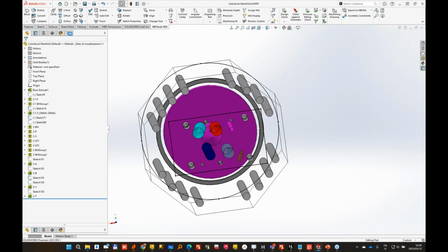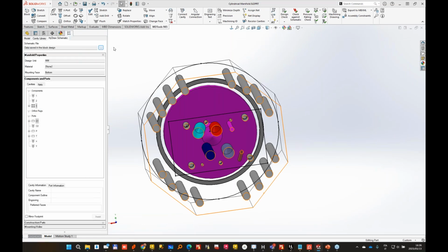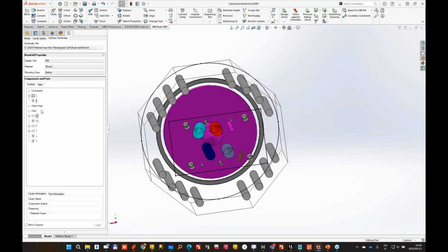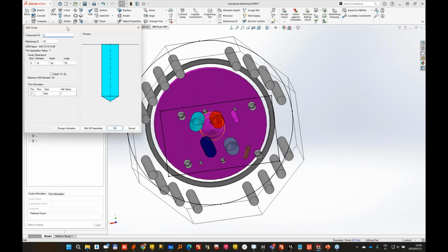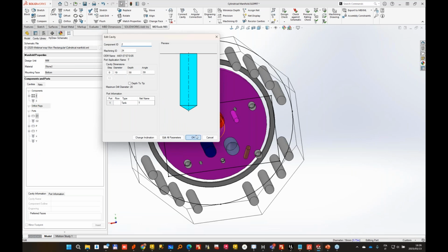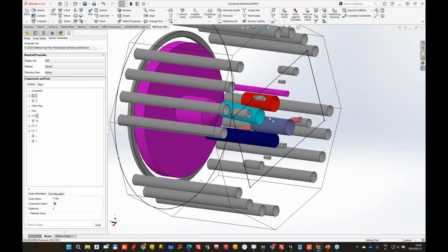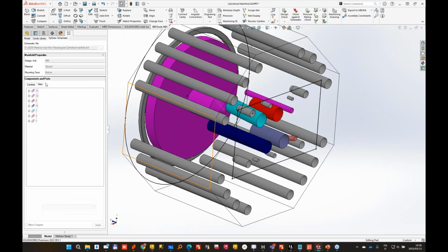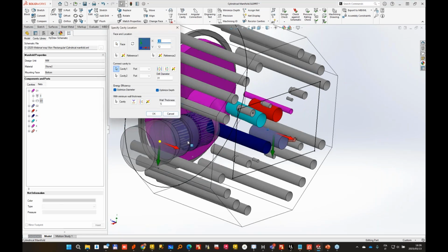So back to our diagram, hydroschematic. Let me load again the same diagram, cylindrical manifold. I have my NG16 valve already placed, which is item 2. And I have all the other valves that are missing. When designing, I can start from the network, so I can take my purple one, I take my counterbalance valve, and I can place it here.